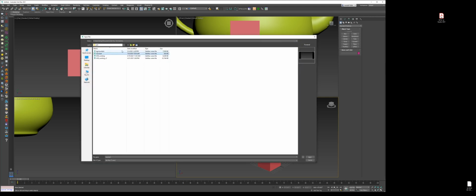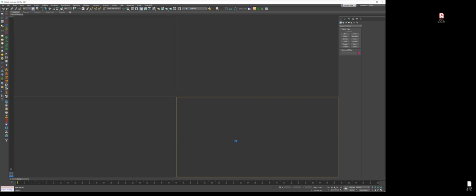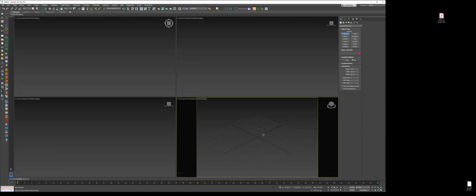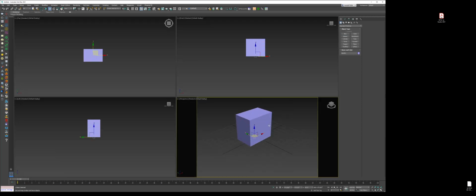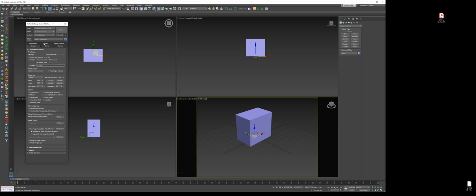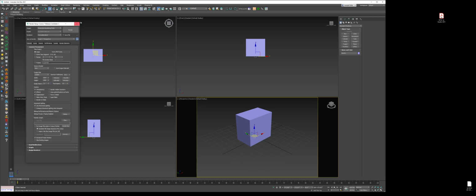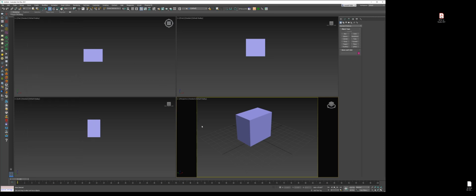And so I have my own max start that I've created a long time ago. This is my go-to file. So I'm just going to reset it. And there we go. As you can see, I have my render engine now, of course, because I use V-Ray for all my jobs. That's what it's set to. But we'll be using Corona Render for the project tutorial. And then my output is 1.5, good to go. So that's how you typically want to set up your 3D Max for the first setup.